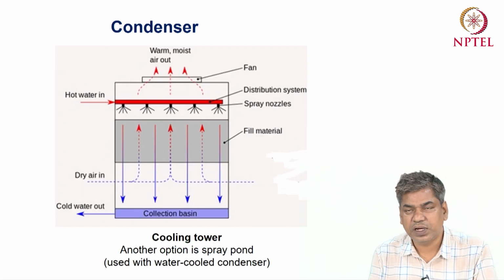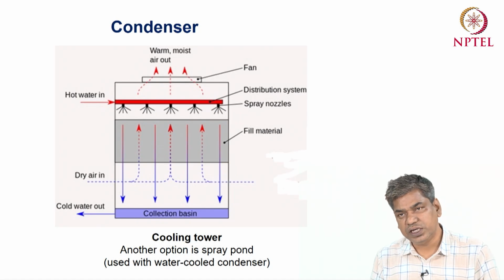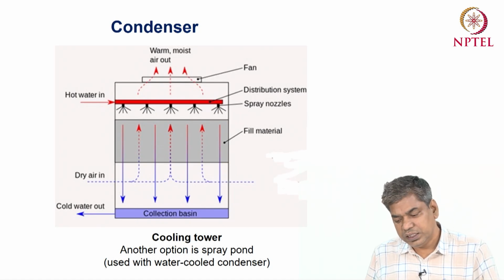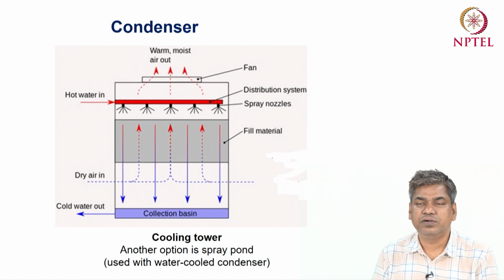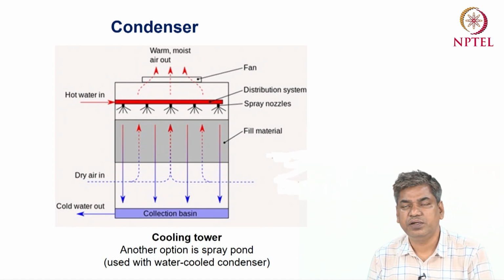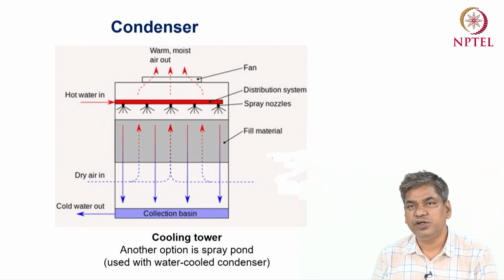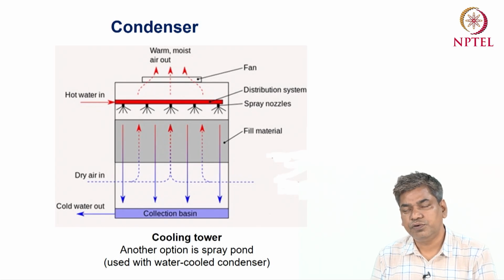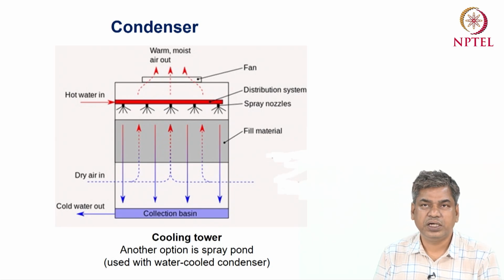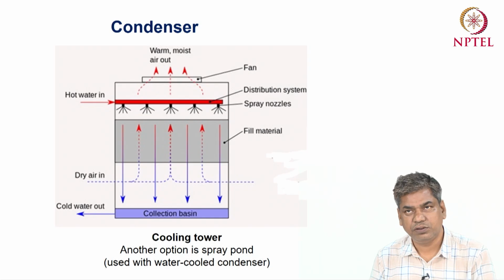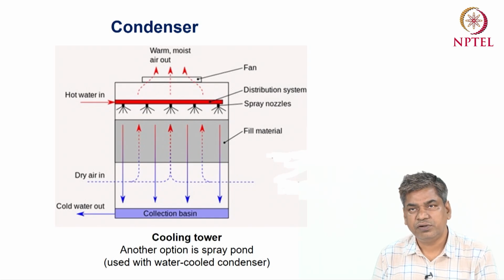And then I am coming to the cooling tower, because the cooling tower is a very urgent or very essential component in the case of a water cooled condenser. The water which is flowing to the condenser will be heated up, and if you want to use the water again for the condenser, we have to cool down that water. Then we can supply that water again to the condenser.